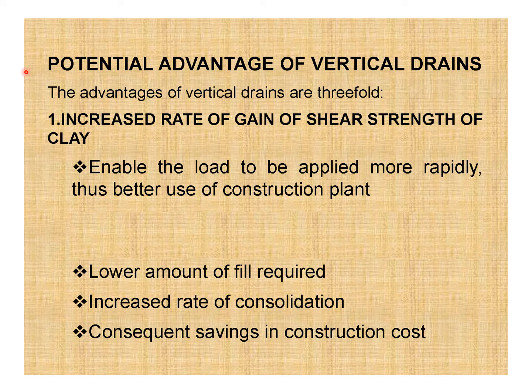Potential advantages of vertical drains. The advantages of vertical drains are threefold. Number one, increased rate of gain of shear strength of clay. That means it enables the load to be applied more rapidly, thus better use of construction plant, lower amount of fill required, increased rate of consolidation, and consequent savings in construction cost.